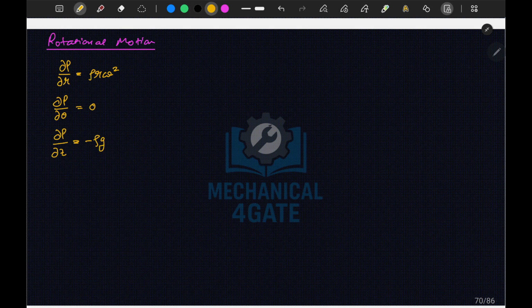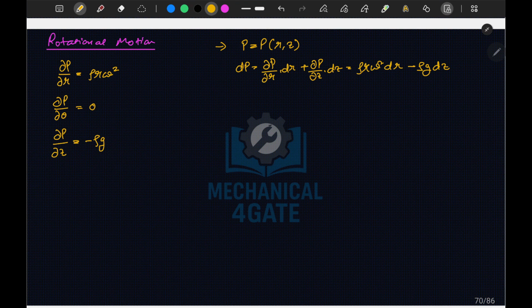And if I write the equation for 2D flow, p is a function of r comma z, so from here I can write dp is equal to del p by del r times dr plus del p by del z times dz, and this can be written as rho r omega square dr minus rho g dz.